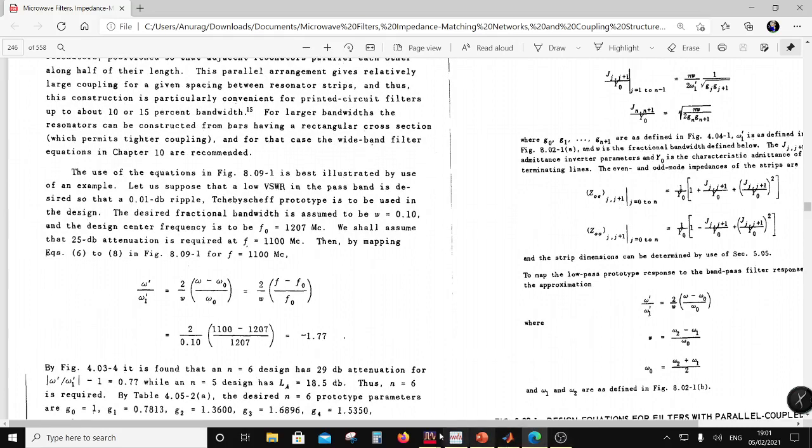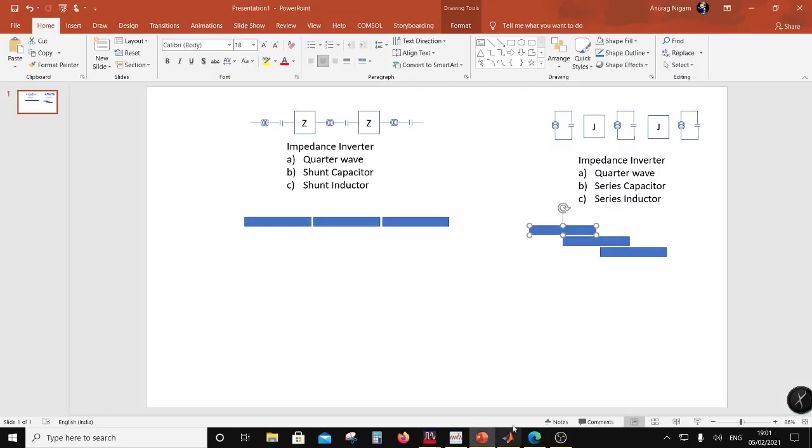So now the way to analyze this is the following. Now this is a coupled line. When we designed a 10 dB coupler, if you remember in the previous section, we designed the spacing and the width of the line. So what did we do? Using that coupling coefficient, we found out Z0E and Z0O, that is even mode odd mode impedances, and from there we established the width of the line and the spacing. Same thing we are going to do over here, right?